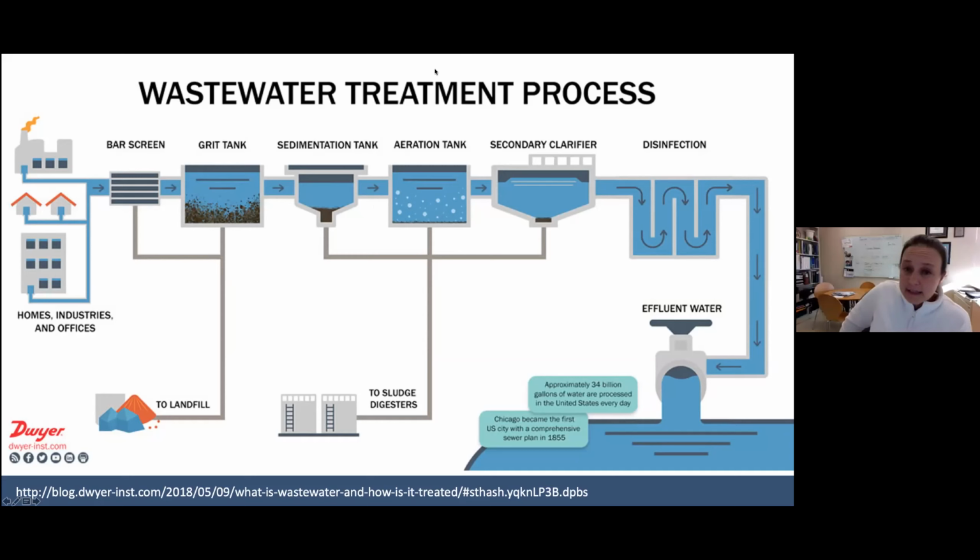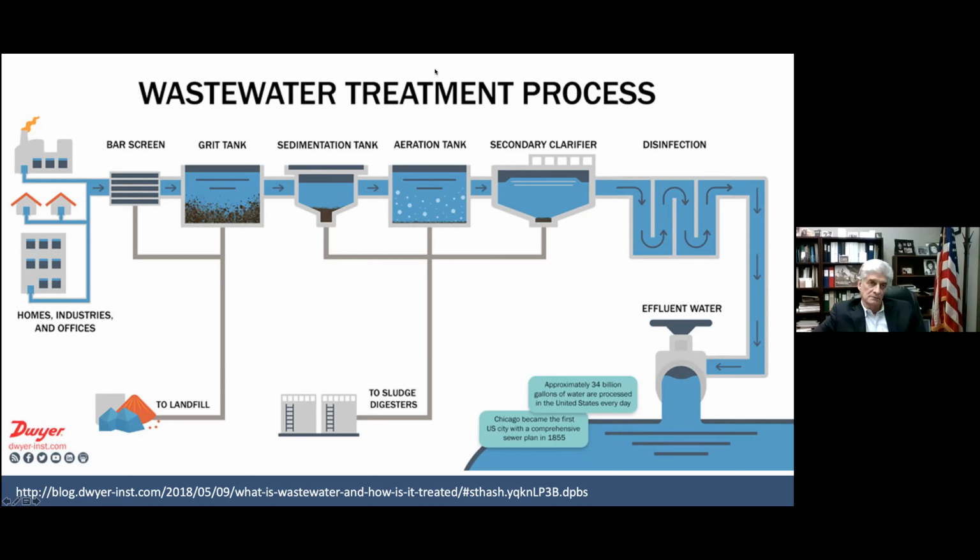Yeah, I didn't. You're asking me these questions, so I know you know the answer to this, but I'll repeat. The American Water Works Association has put out a statement because obviously everyone is concerned about this. When we meet our disinfection standards in drinking water, it's much harder to disinfect bacteria than it is viruses. So the assumption and all evidence to date is that if we meet our disinfection for bacteria, we take care of viruses. And SARS-CoV-2 does not seem to be unique in that. Okay, thank you.